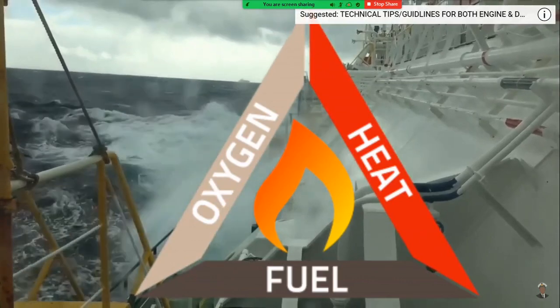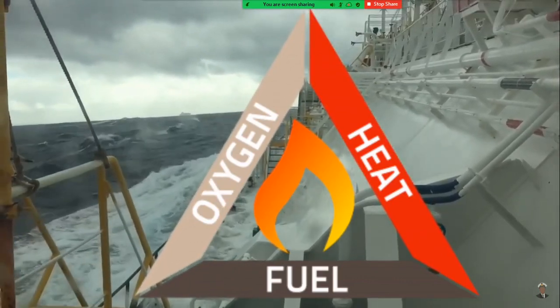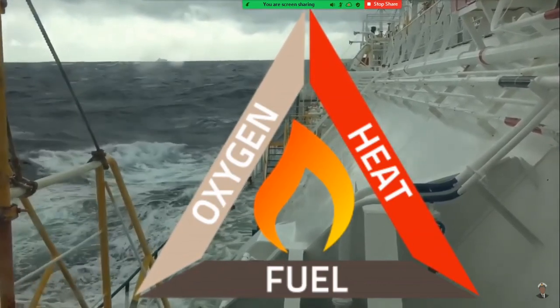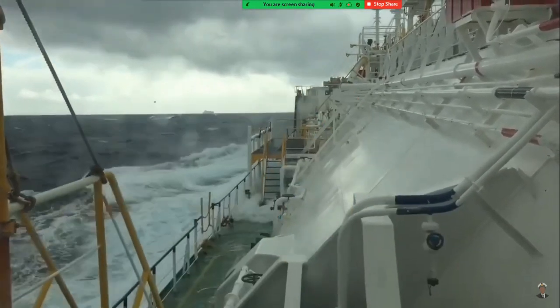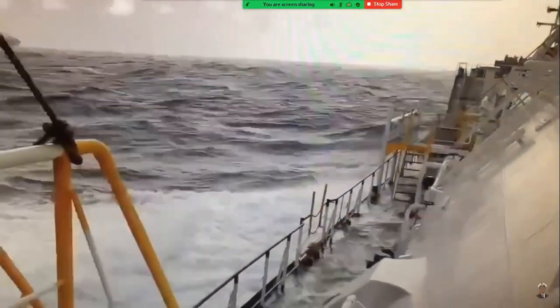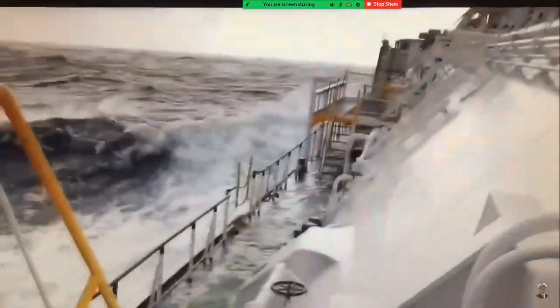Inert gas inerts the atmosphere of the tank by keeping the oxygen content to a minimum, which breaks the fire triangle. The oxygen content in the inert gas is about 5%, and the minimum oxygen concentration required for combustion is 8% on board a ship. To be on the safer side, the oxygen content in the inert gas is usually kept at 2 to 3%.